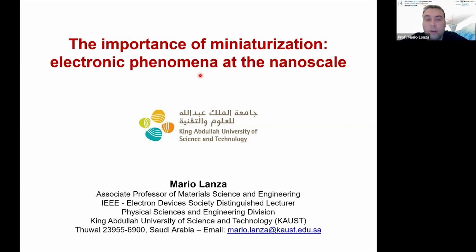For memristors, normally what we adjust is the diffusivity of the metal into the resistive switching material, the thickness of the resistive switching material, things like this. So there is no magic recipe. You have to check the material you are working with, which are the electrodes, and then make decisions on how to adjust that. But normally, thickness of the material, device size, and diffusivity of the metal into the resistive switching device are the main factors to take into account.